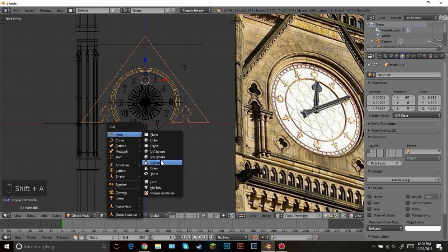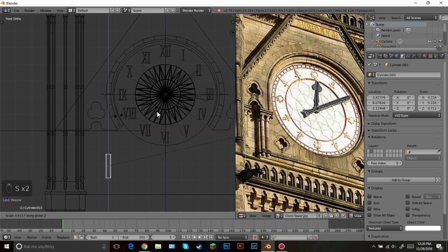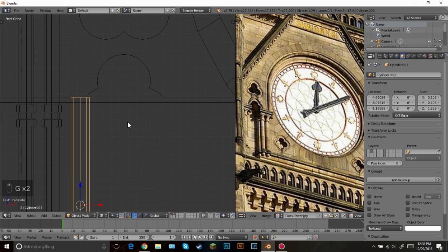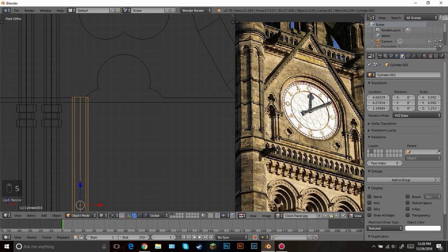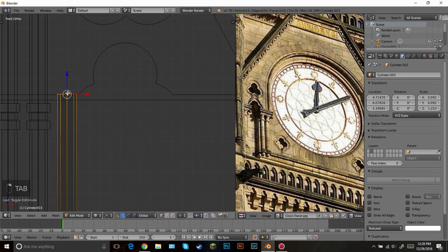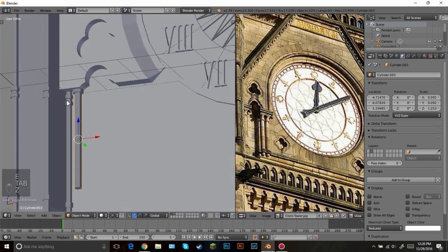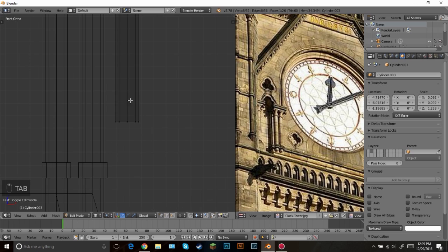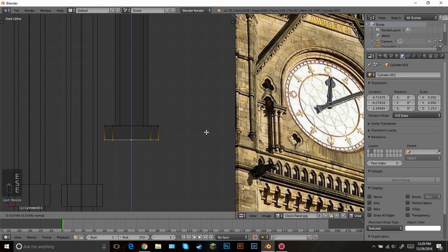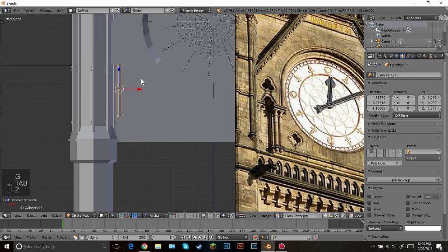Okay. Alright, so now let's make these little cylinders right there. So add in another cylinder. Where to go? Over there. Place it right here, scale it down, and then scale it along the Z. Okay, scale Shift Z, and then place it right about there. I'm not going to make it totally exactly like this picture. I'm going to make it like what I want to make it. Okay, so it looks like there's extruded edges, so extrude that one up, and boom, right into there. Okay. Same thing on the bottom. I'm going to Alt right click, Extrude Scale, and extrude it down. And it looks like there's these like loop cuts in the middle, and I'll add those in just a second.